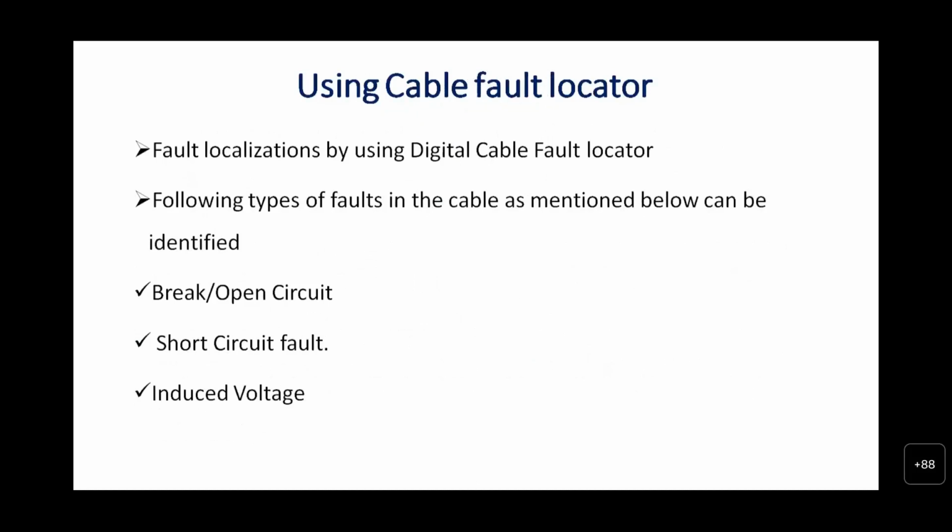The other method is the cable fault locator, that is, fault localization using a digital cable fault locator. Some divisions have been using it, but experience differs from division to division and user to user. The following types of faults in the cable can be identified using this digital cable fault locator: break, that is open circuit, short circuit, and induced voltage.